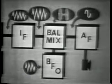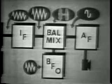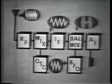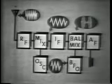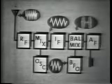All we did was reverse the process of the transmitter. This is called reference frequency generation. The standard audio circuits will now select and amplify the audio signal, or the audio amplitude variations, the original intelligence that we have transmitted. Thus, we have created a single sideband receiver.